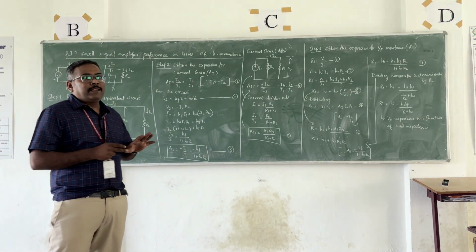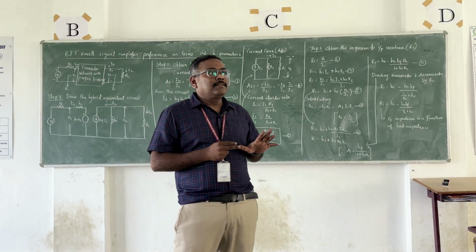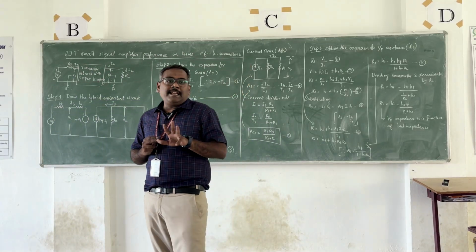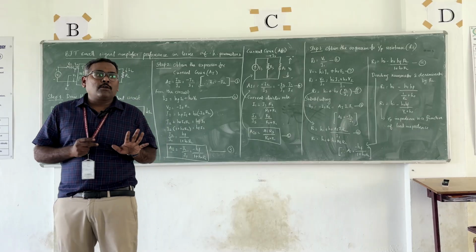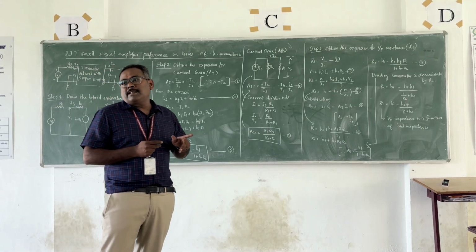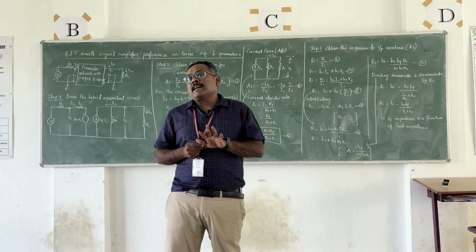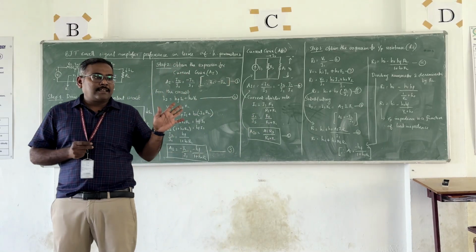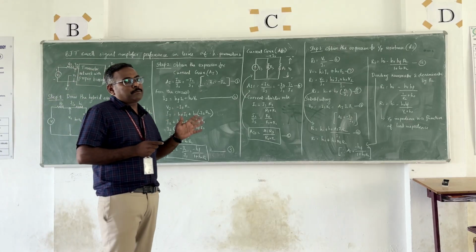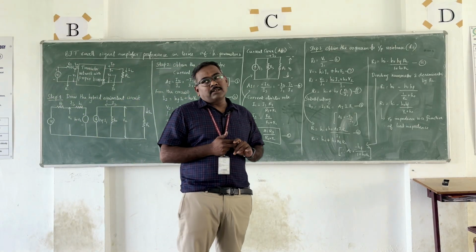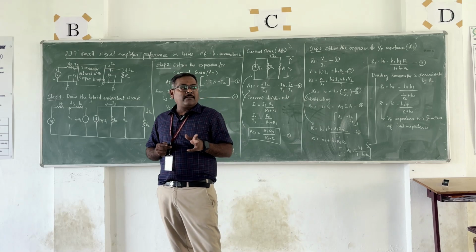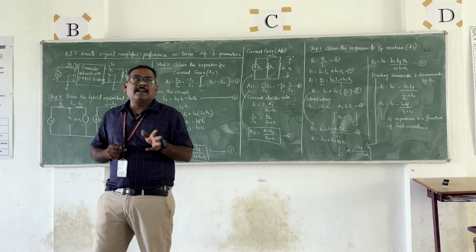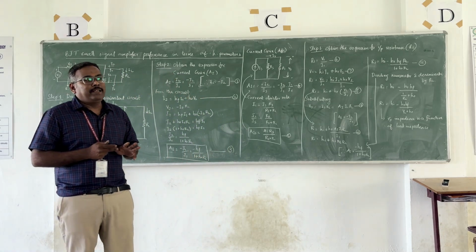Okay. So already we know that the BJT is a 3-terminal, 3-layer, 2-junction bipolar device. Bipolar devices in the sense the current conduction is due to both majority and minority charged particles, positive and negative. Okay. So we have 3 configurations: common collector, common base and common emitter.